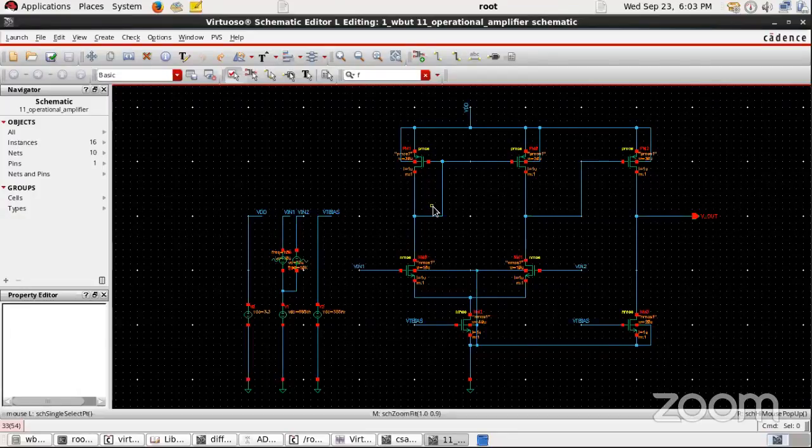So what should be the output gain? That is my question. You have connected two amplifiers. Now what will be the gain at the output? It should be the sum of both the amplifiers. At the common source stage, you got a gain of approximately 43 dB, and for the differential stage it was around 47 or 49 dB, I don't remember. Okay, 49. So it should be the sum of both these gains, approximately somewhere close to 90 dB.